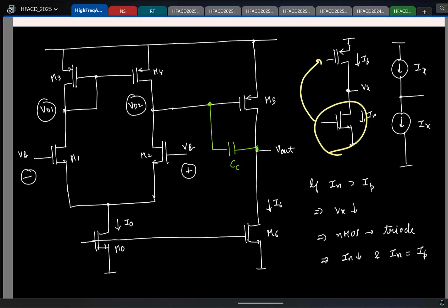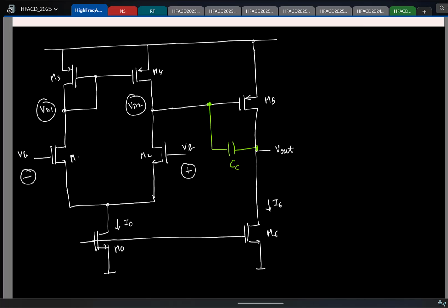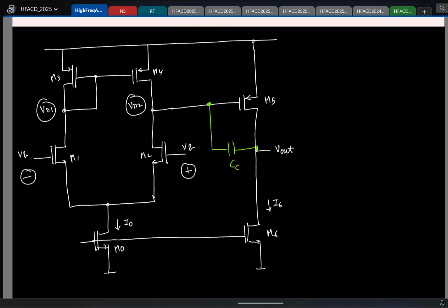Okay, so if this is clear, now we know that we need to have some feedback mechanism to set one of the current sources based on the other, and as such there is no feedback mechanism here, because both of them are independently biased. But we are engineers, we should never lose hope, because finally where is this op amp being used? In some kind of global negative feedback.